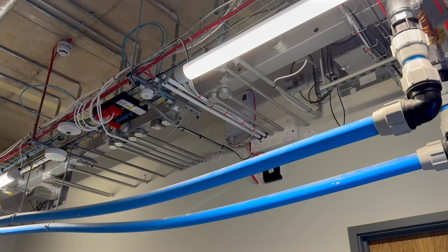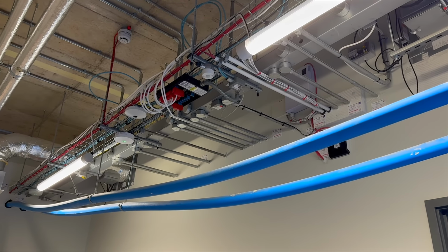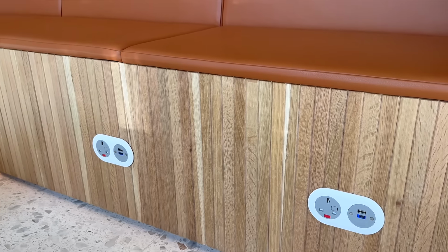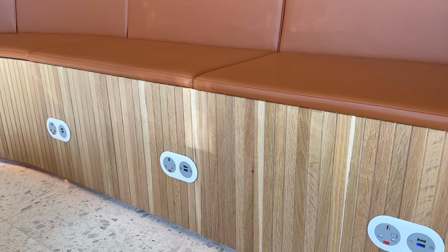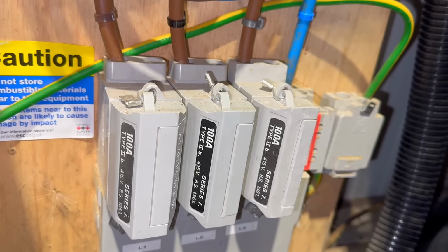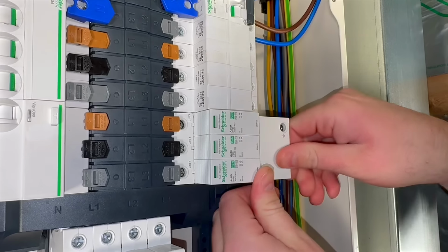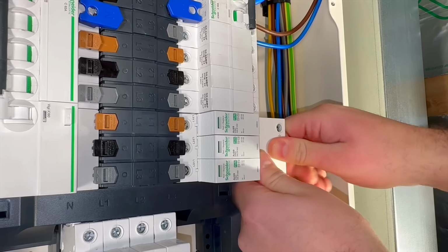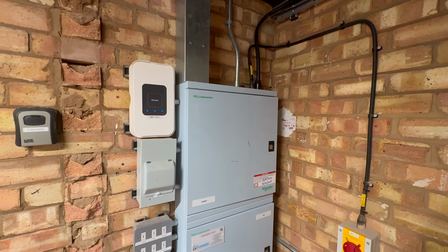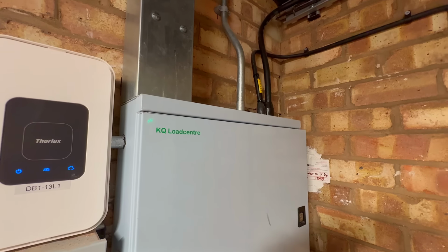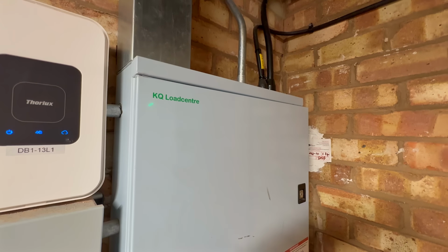And this is why that 10 metre figure exists. It marks the point where the effect becomes significant enough that additional coordinated protection closer to the load should be considered. So let's apply that to a typical small industrial unit. The supply enters at the main distribution board. At the origin we install a combined Type 2 and Type 3 SPD. The submain then runs 25 metres to a remote distribution board feeding control panels, drives and IT equipment.